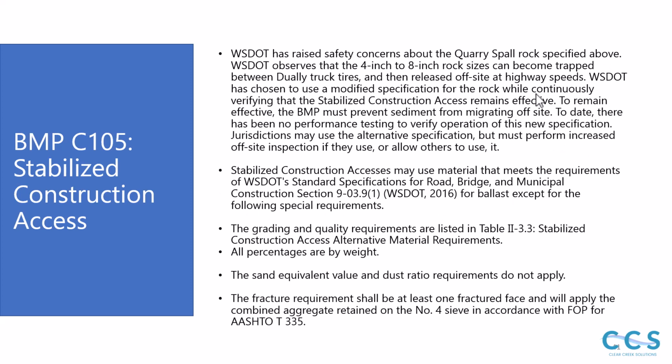WSDOT has raised safety concerns about the quarry spall rock specified above. WSDOT observes that the 4-inch to 8-inch rock sizes can become trapped between dolly truck tires and then released offsite at highway speeds, which is not what we want.